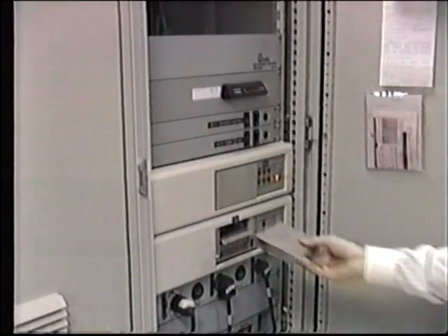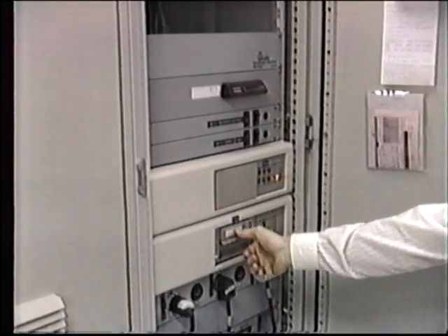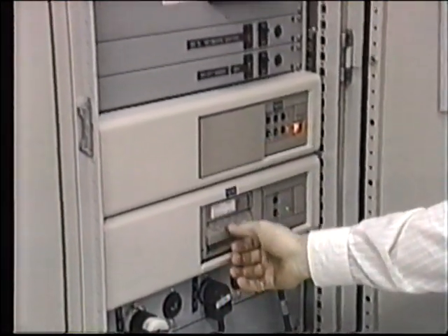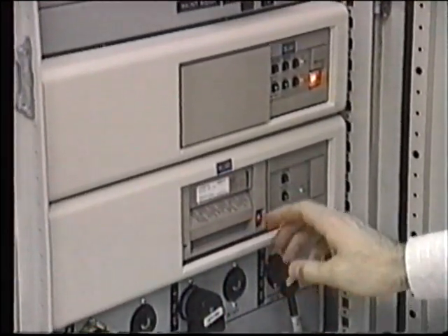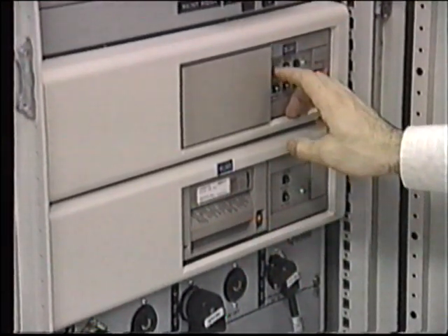The Scada system is an absolutely vital function that cannot be allowed even a momentary interruption. We have already discussed this subject of uninterruptible power supplies in an earlier videotape in this series. To carry out functional tests, it is usual to apply diagnostic software specially designed to troubleshoot master station equipment.